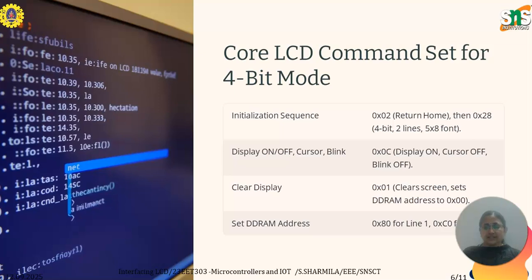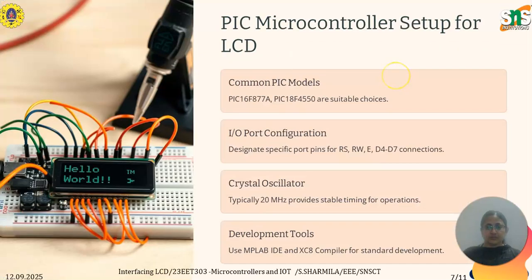Clear display: 0x01 clears the screen and sets DDRAM address to 0x00. Set DDRAM address: 0x80 for line 1, and 0xC0 for line 2.